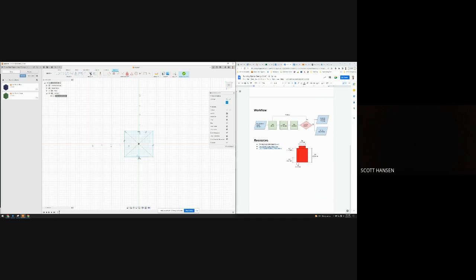And you'll notice that those dimensions that were created, those were in millimeters, or excuse me, inches. But I really want to be working in millimeters for this particular exercise. So let me go to my document settings and switch that to millimeters, or verify that that's in millimeters. That's probably way too big now. Anyways, this is going to be looking at the top view.